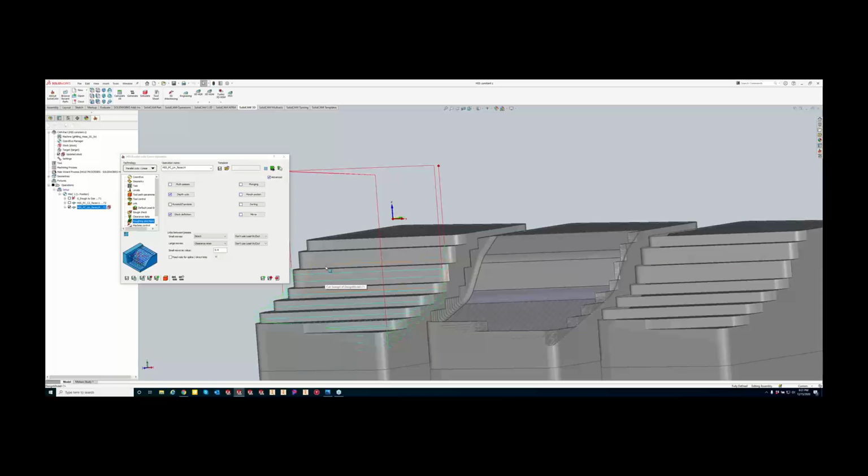Now, one thing that I think I forgot last week, we started getting on this road and then got the wow factor going, but I didn't cover the plunging or the morphing pocket or the sorting or the mirror. So the rotate and translate is the exact same thing as what you guys have used in the past with the transform. Before, HSS could not use the transform functionality. Well, in the newer versions you can now, so that's going to cover your translated and rotated surfaces as well as your mirroring.